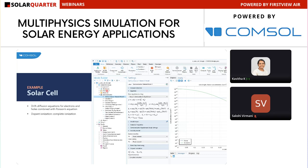Then you model the geometry. Then you assign materials to the geometry that you created. Then you set up as many physics as you want. Here in this example, it's semiconductor, but you can add as many physics in the same desktop interface. Then you mesh your geometry. Then you perform the study, you simulate, and you can visualize the result. So COMSOL follows a top-down approach for the modeling workflow. And for any type of physics that you solve, you will be using the same modeling workflow in the same desktop.